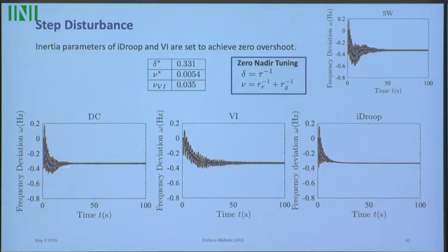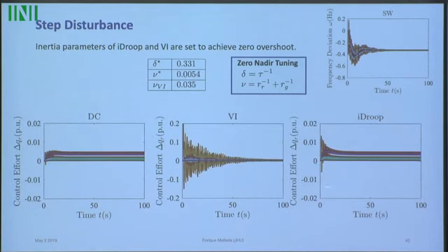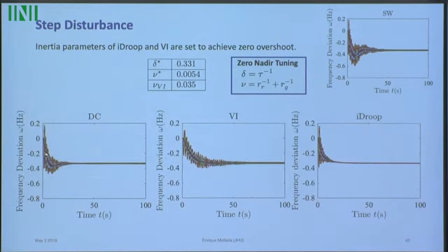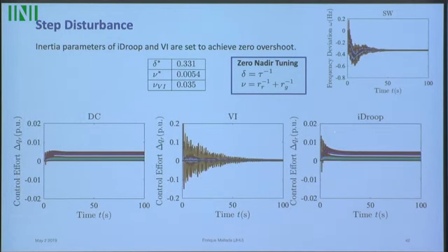So essentially, instead of having this overshoot, you just have a first order response. And it's faster than what you will get if you use large virtual inertia to get this critically damped response. But more importantly, the control effort is not drastically different than Droop control. So you can remove this overshoot without necessarily too much additional control effort.